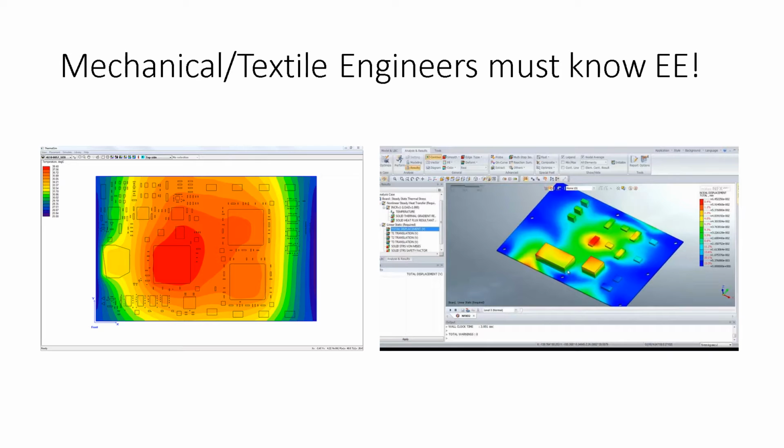As you can see, each one of the parts stays within its own thermal realm. There's some coupling in the green there, but we're presuming that essentially, for all intents and purposes, this is a pretty well modeled and well approximated circuit. That red piece in the middle, you'd have to check the data sheet to make sure that's not getting too hot. And you have to remember, what makes heat?